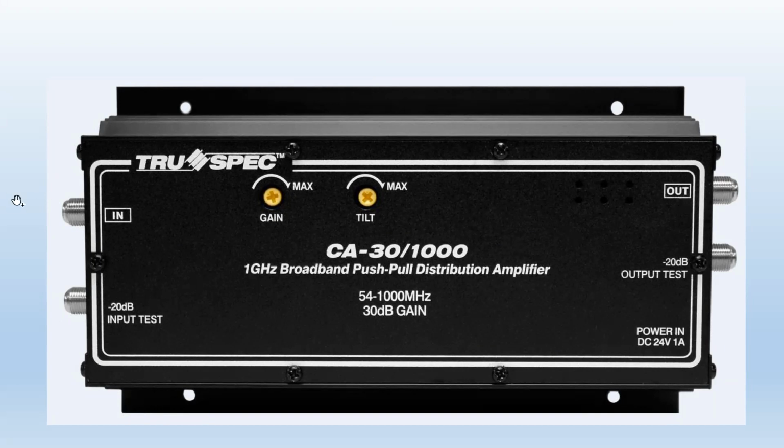Now, notice normally when the signal comes from the city, from outside the building, it gets strong. Maybe 20 dBs, maybe 40 dBs, whichever the strength of the signal coming in. If you wanted to connect straight to a TV tuner, it would be too strong for the TV.